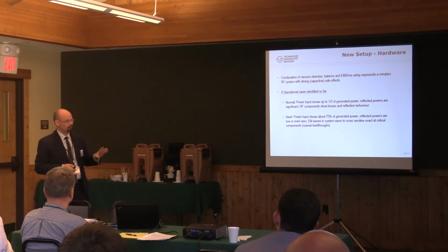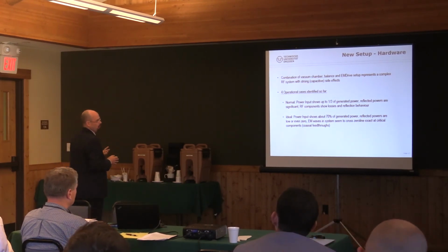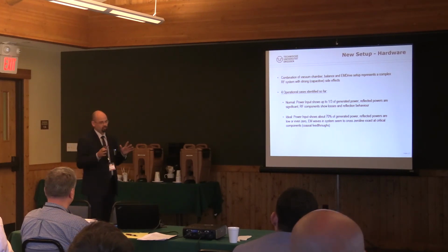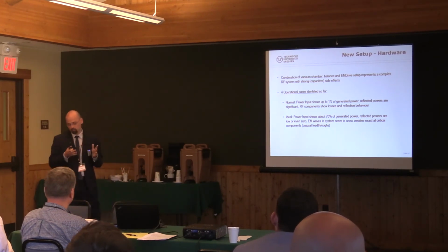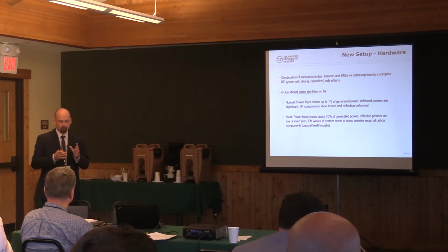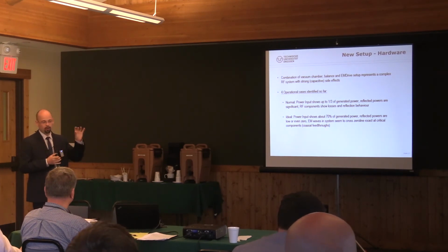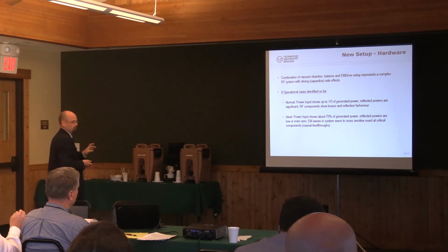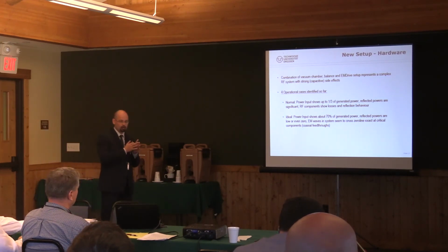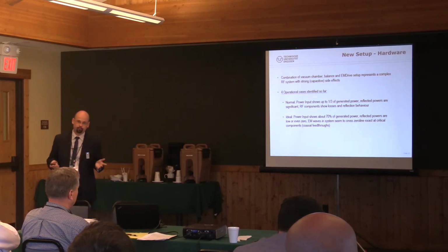Today I think it's a very lucky case that all the waves inside our system interfered and lay at positions such that the zero lines of our electromagnetic waves were exactly at the position of our critical components. So if we have, for example, our feed-through, and the wave has a zero line crossing at the critical component, the power will go through this component without being damped or reflected.